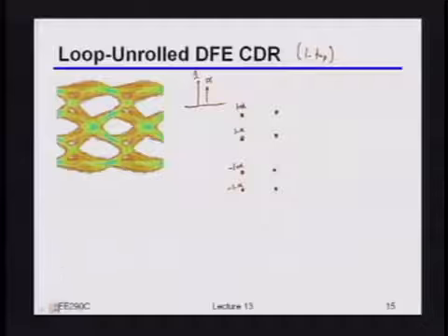So let's start with the simplest thing. Let's say I'm just transmitting a clock pattern, meaning I'm sending 1, 0, 1, 0, 1, 0 at the full data rate. If I was doing that, what would be the arcs that I should draw in here? If this is the previous bit and this is the current bit, which analog levels can I start from in the previous bit, and which analog levels can I end at in the current bit? By the way, I'll give you a hint for a clock pattern. The previous bit is always different than the current bit.